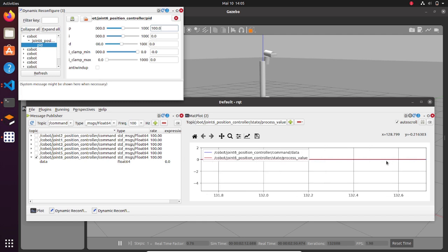So commonly we can see that it is not recommended to put, as a first guess, a higher value in a proportional control, because otherwise the joint is acting weird, and it seems that we are losing the control of that joint.